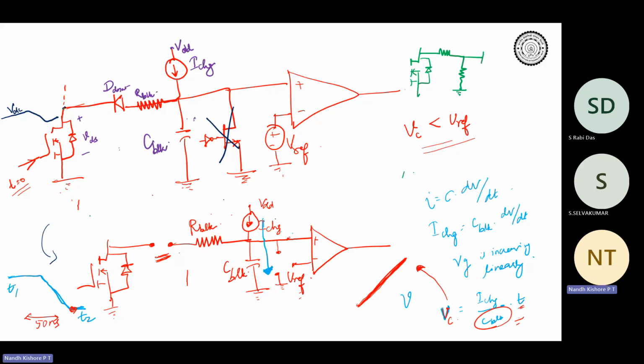And then you connect across this. Okay, so you will connect to this point. So basically you are sensing what is VDS into whatever is the ratio of the resistive divider, R2 by R1 plus R2. Do you understand? We step down the voltage. Okay, that is also done.